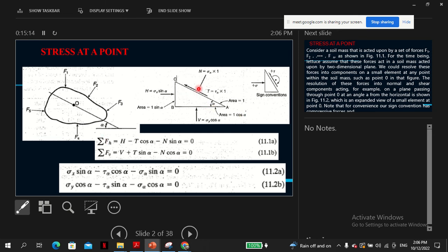If by now you know that this is civil engineering, we need our forces in the horizontal direction to be 0. We usually have 3 equations. The summation of moments should be 0. Summation of forces in the horizontal direction should be 0, and summation of forces in the vertical direction should be 0.